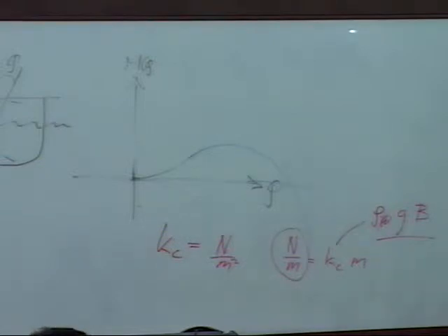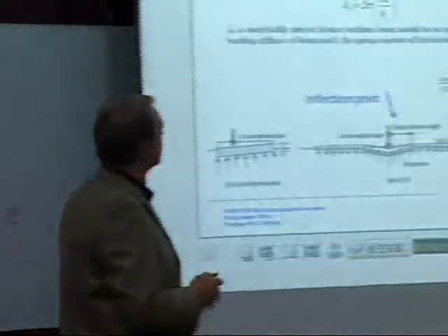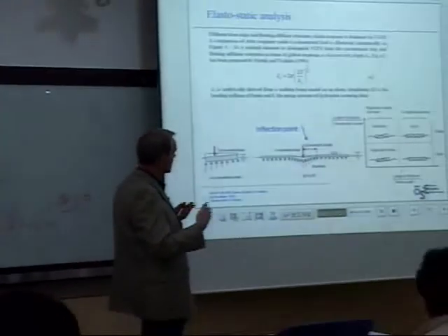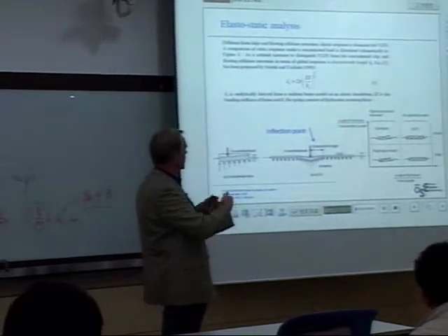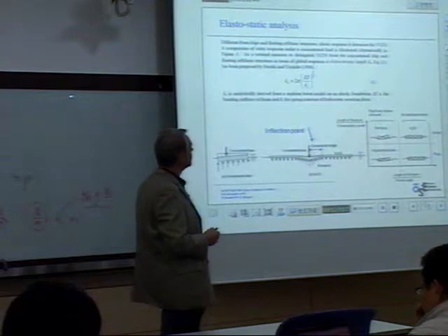But the thing is, if you have a very stiff beam, and that is the bending stiffness of the beam, you'll have a very large characteristic length. The length says something about the stiffness and how this long floating beam will bend, right?